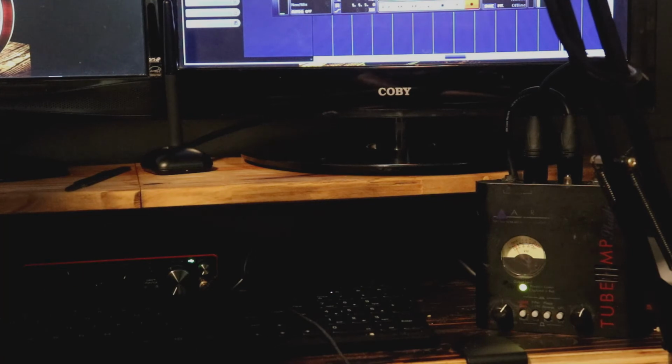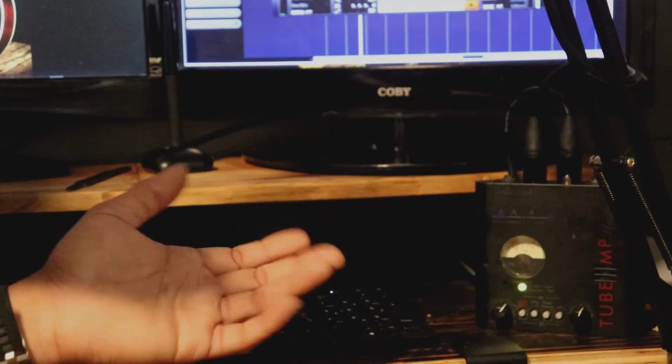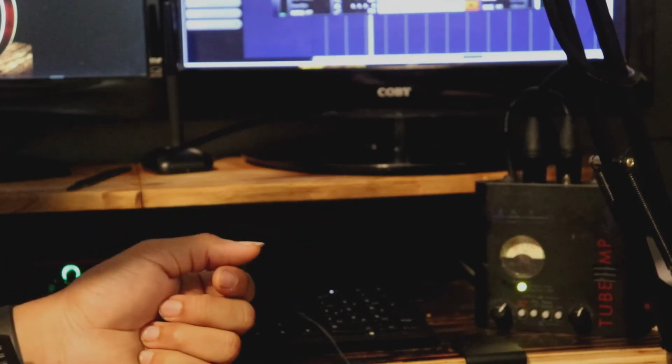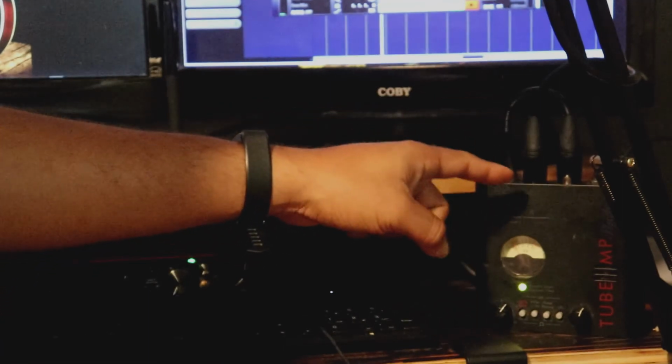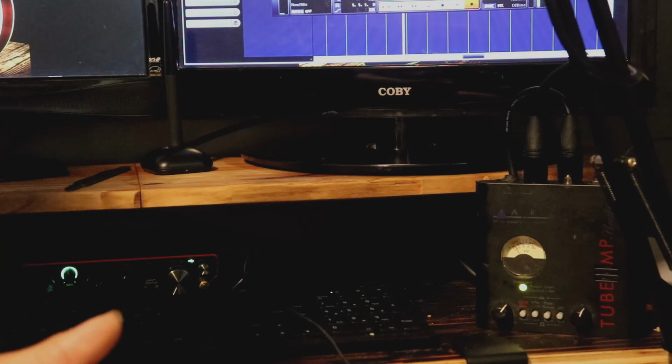Though, as I said before, I can't do that if I want to use an op amp EQ and have enough headroom to withstand the output of this preamp. Because 9 volts isn't going to give me a 17 volt input.